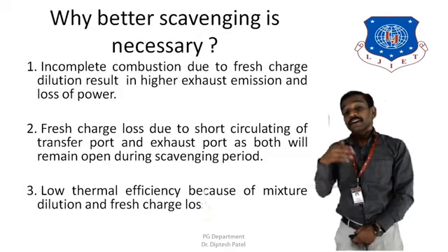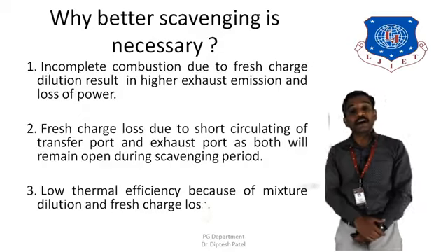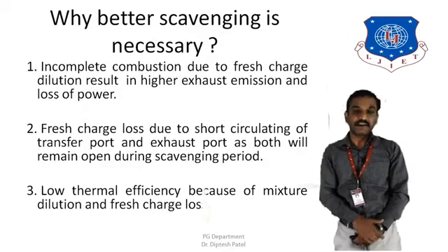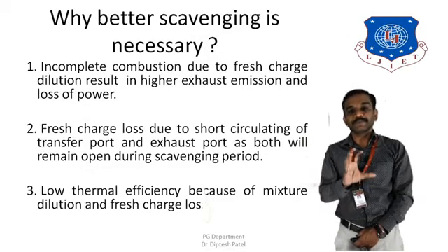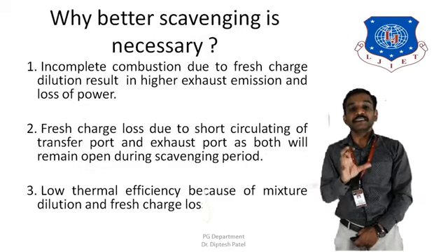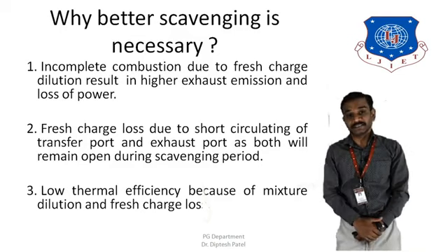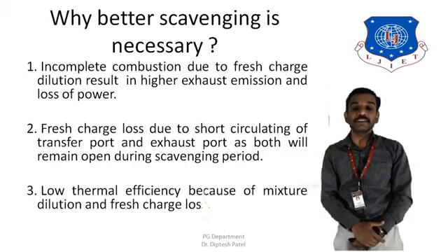Now why is it important to have this scavenging process? Why is it necessary? There are a few incomplete combustion gases that would dilute the fresh charge if they are not completely removed from the engine cylinder.